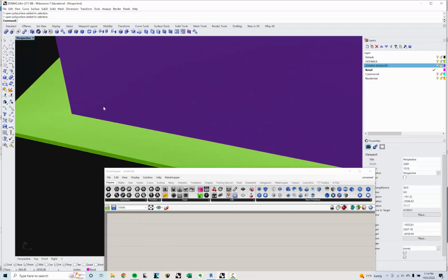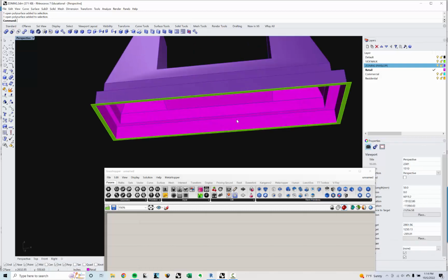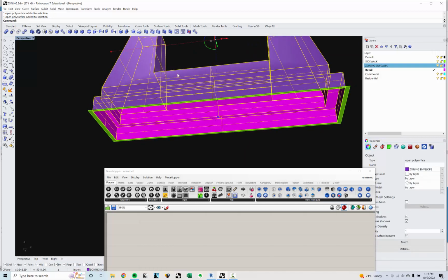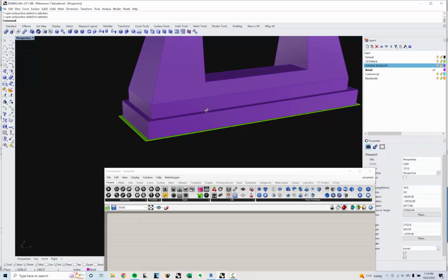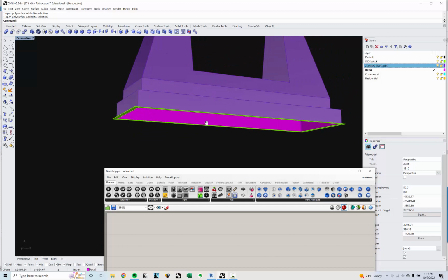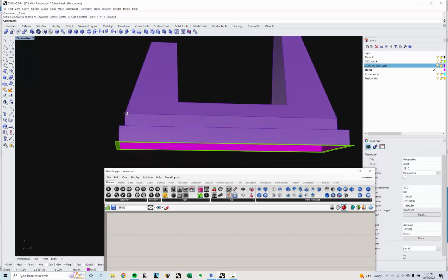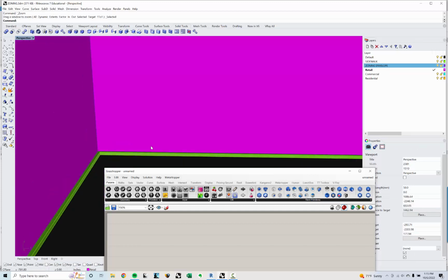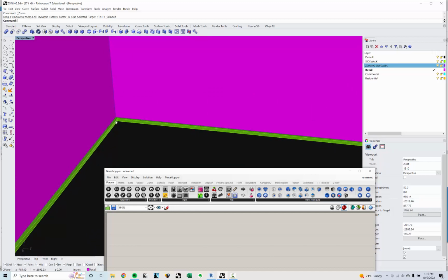The one other thing I would mention is I found that this works a lot better if you take out the underside of it so that it's just a surface. We don't want it to be a solid for when we start to get into Grasshopper. And we also don't want this to be right at the property line. So if I zoom in here real quickly, you see that it's actually set out. I set it out like 3 inches because we don't want our massing in our floors and everything to kind of, this is just an analysis.